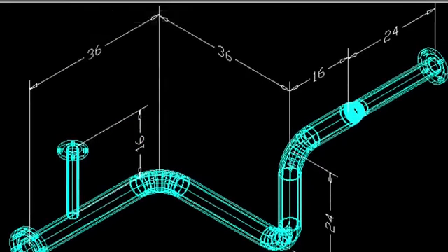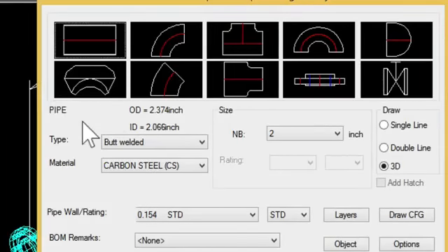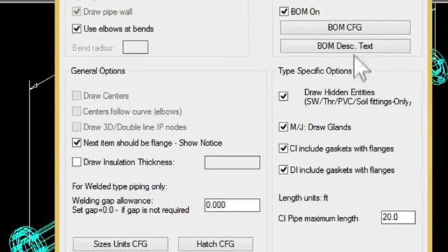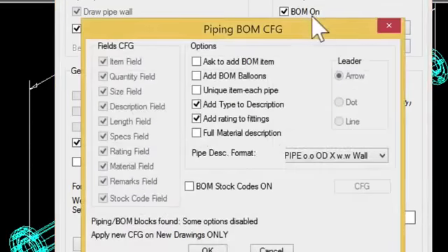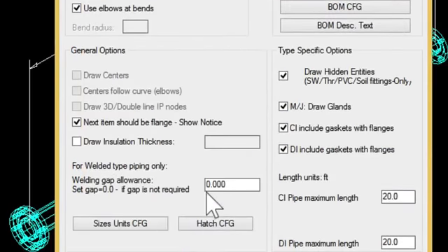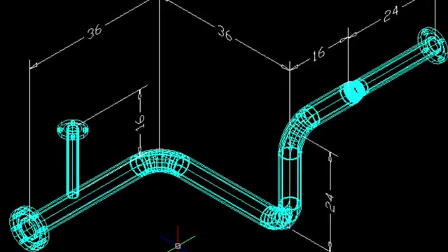During the last few minutes, Mech Q has been counting all of the parts in our piping spool. This allows us to create a bill of materials schedule, or what we call BOM. First, let me check a couple of settings. Notice in the options menu, I'm turning on the bubble option. And I've also specified a dim scale of 12. Dim scale sets the sizes of the table based on the final print or plot scale. See our attached cheat sheet for more on this if you're new to CAD.